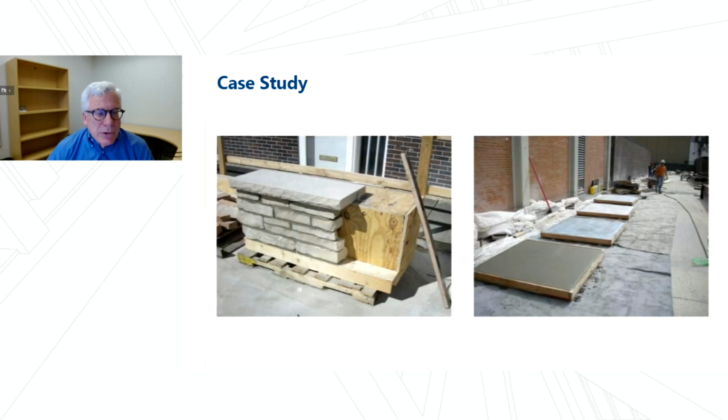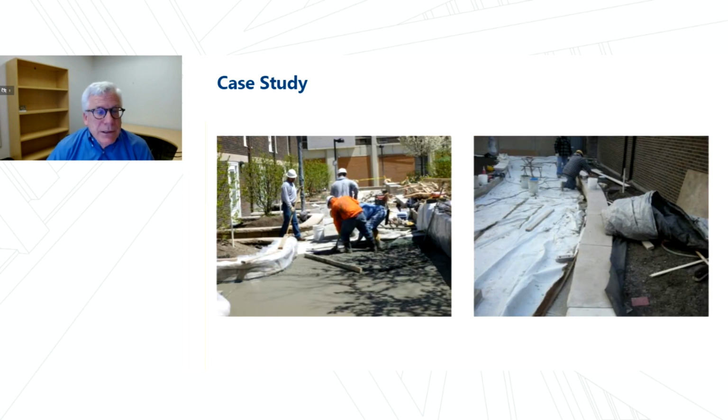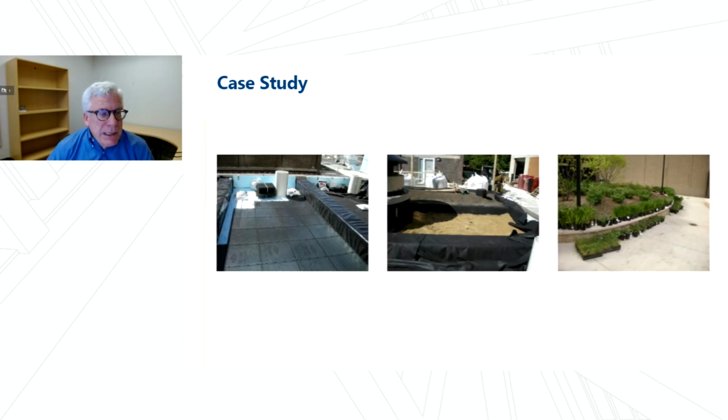One thing we encourage with all this, because many of the top surfaces are aesthetic, is to do mock-ups of the repair techniques. Once again, to verify what you're getting and to also verify the ability of the craftsman performing the work. And then finally, laying out the concrete, curing it, as Jason described, and then installing things back in the planters.